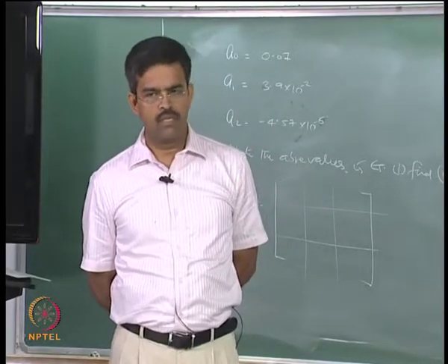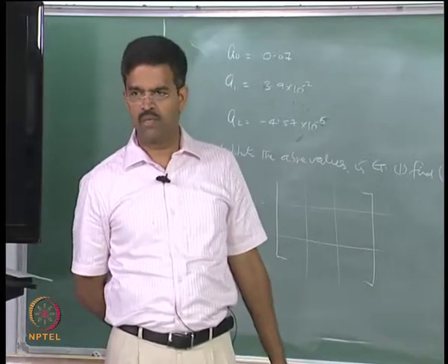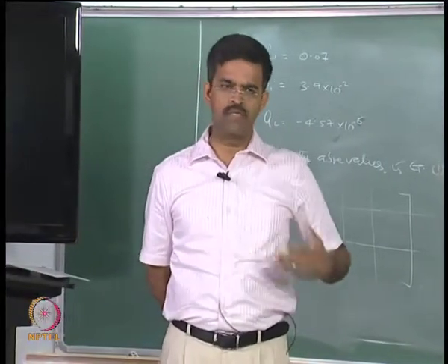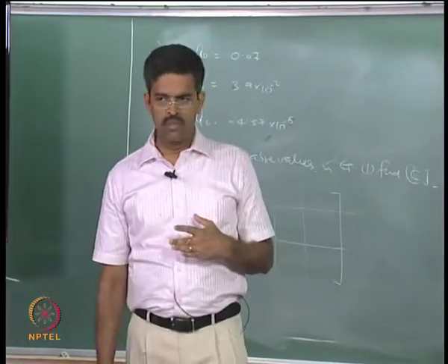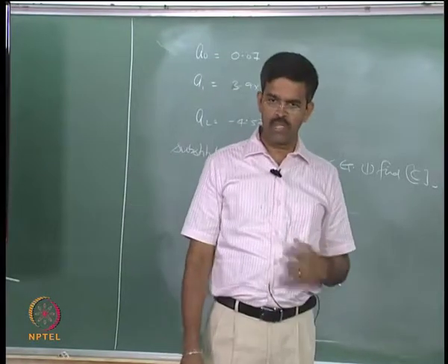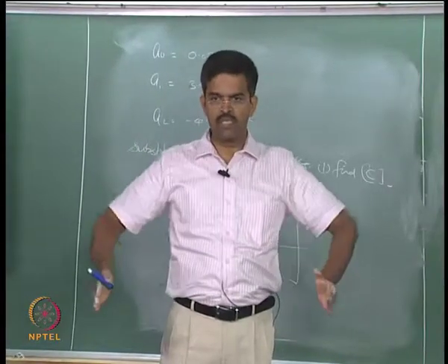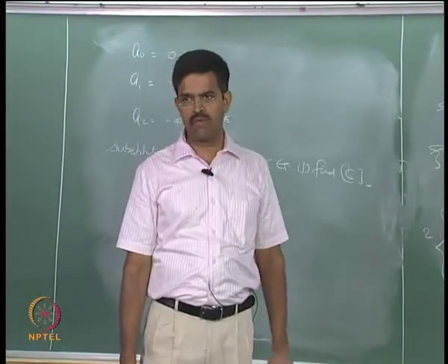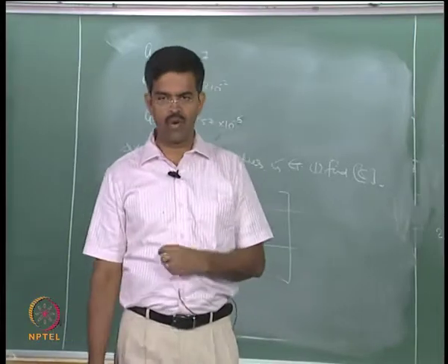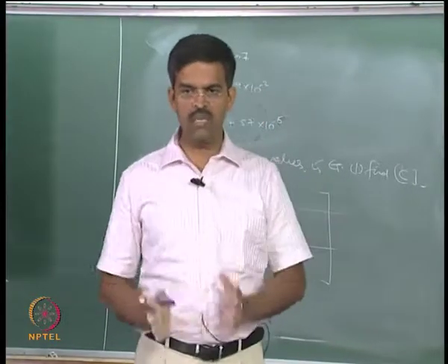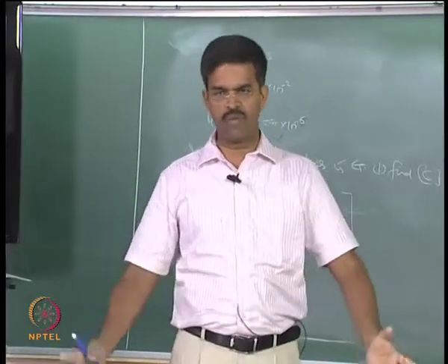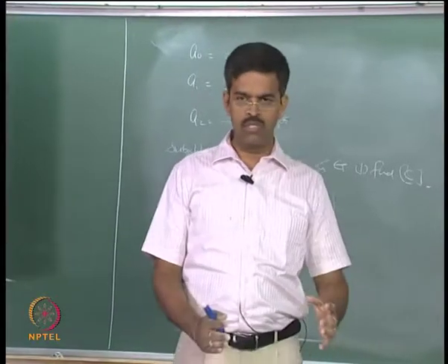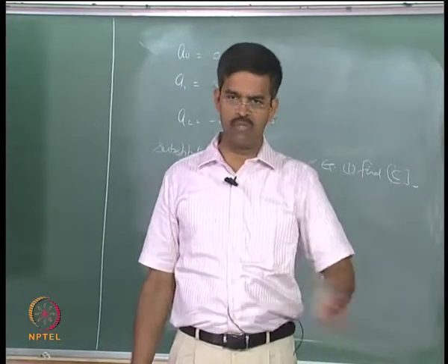Okay. So, these are the three methods we have for estimating the damping matrix, which are commonly practiced in literature for structures which have a wide spread of frequency ranges. We can go ahead with Rayleigh damping for the TLP because we have two distinct sets of frequencies, though we have 6 frequencies, one set is stiff and one is flexible.